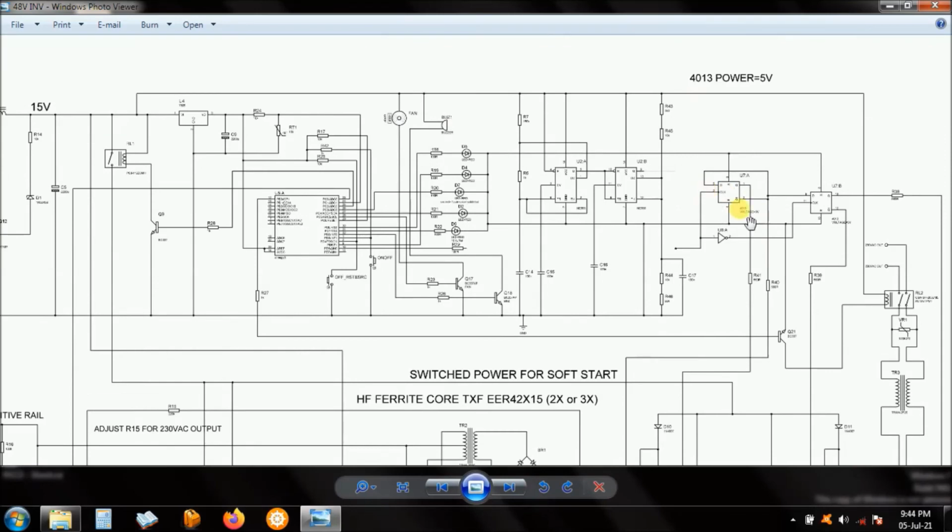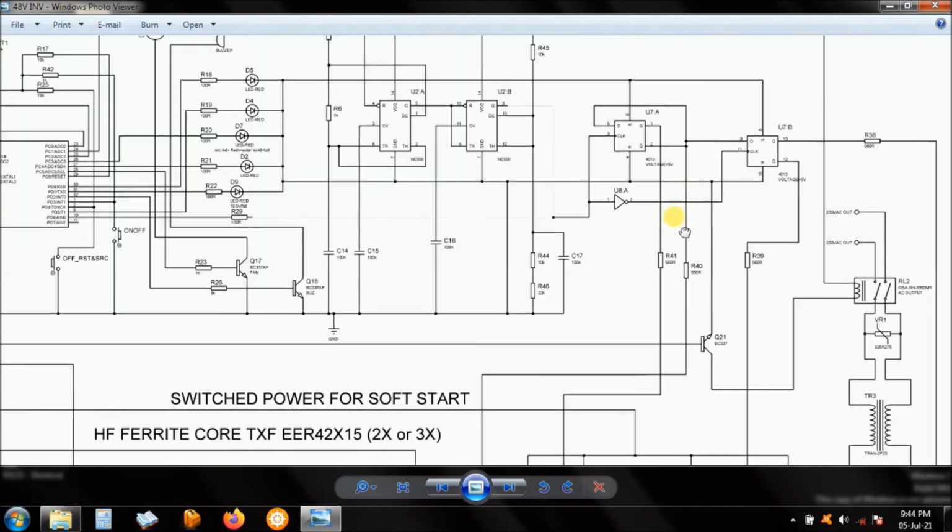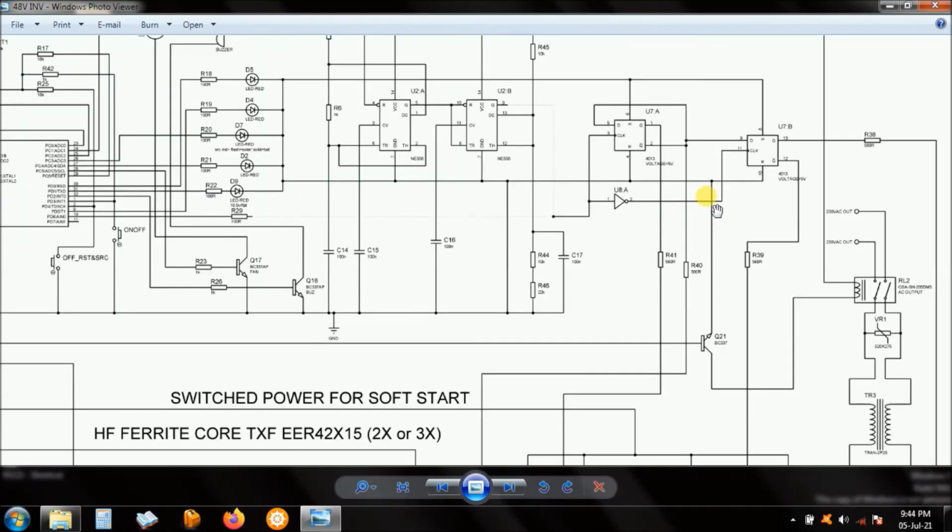That also determines how you connect these four outputs here. And remember, pin number 1 and pin number 2 are always alternate. This is a D-latch. Pin number 13 and pin number 12 are always alternate. As I have explained, in most designs pin number 1 and 12 are connected to the high MOSFETs, or vice versa.